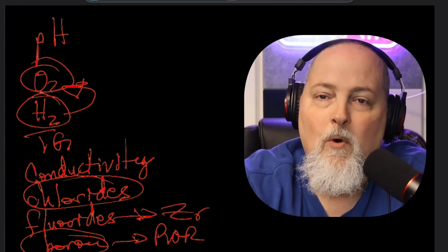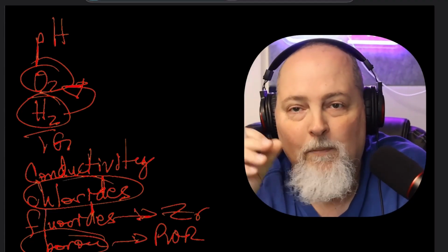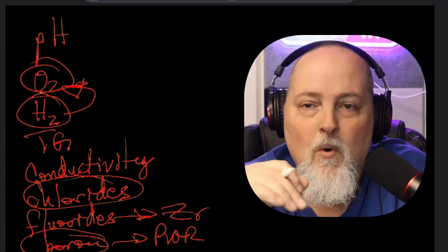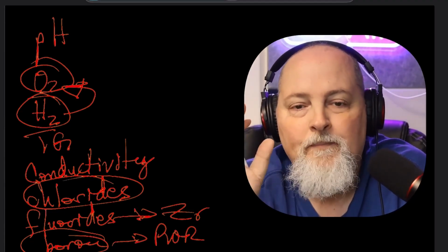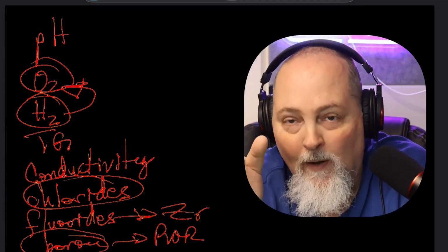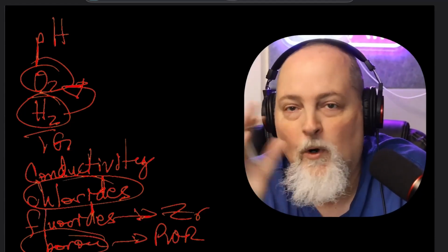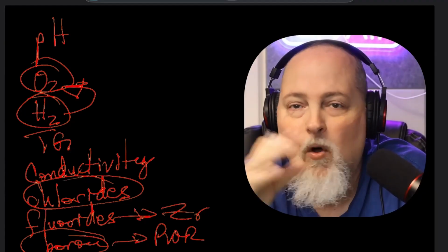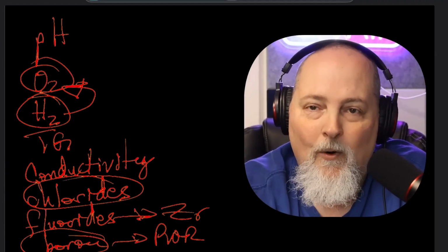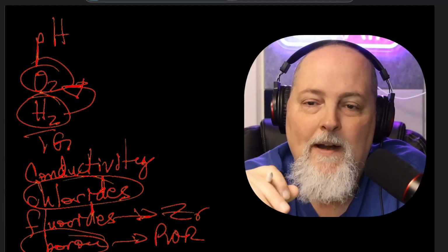We start these boron pumps. It fires a couple of explosive valves and injects boron into the reactor. It injects enough boron that if we're cruising along at 100% power, with all the control rods completely out, we can shut down the reactor.